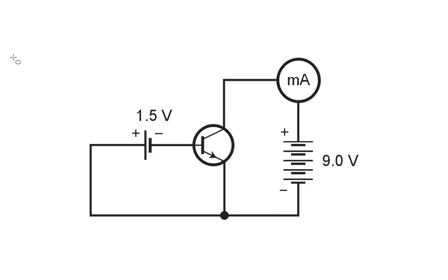Well, it's a good thing that this polarity configuration is what it is, because otherwise we'd likely burn the transistor out. There are no current limiting resistors in this circuit, as you can see. But note the polarity of this cell right here. The polarity puts a negative 1.5 volts on the base, ensuring that this device is going to be cut off, so we're not going to see any current here.